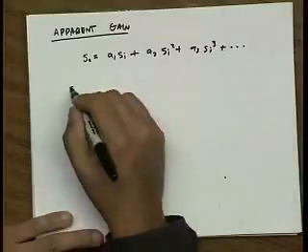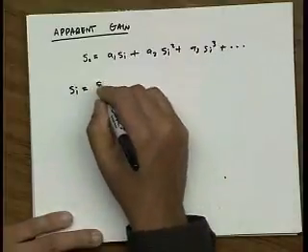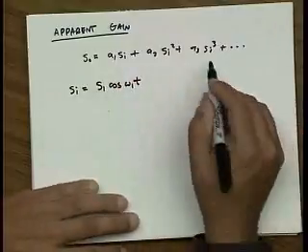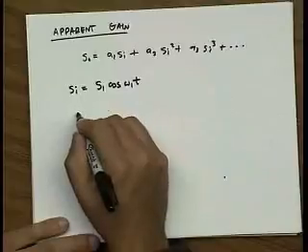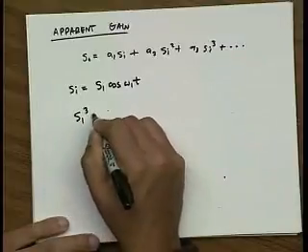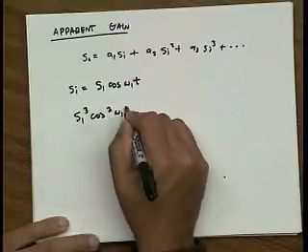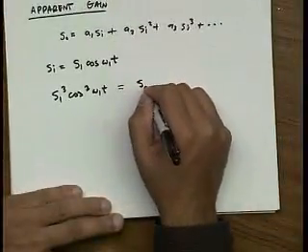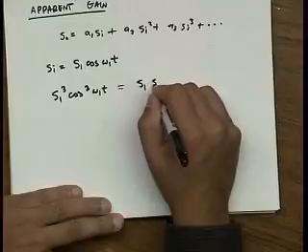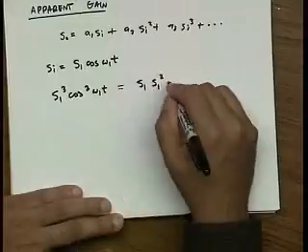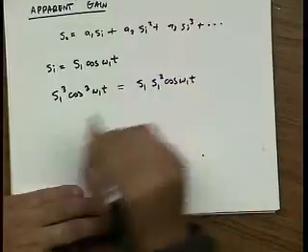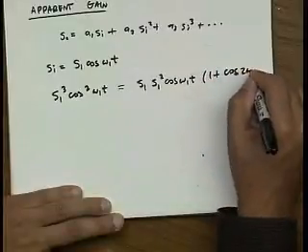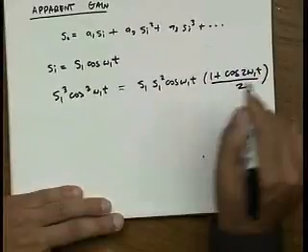So remember, if we put in an input amplitude, let's say S1 cosine omega 1t, and we look at the cubic term, S1 cubed cosine cubed omega 1t, I can never remember these, so I just do it from scratch. I can write this as S1 squared cosine omega 1t times cosine squared, which I do remember. That's (1 plus cosine 2 omega 1t) divided by 2.